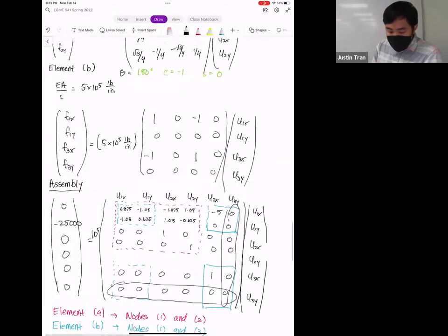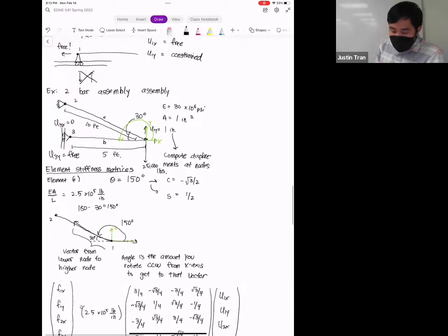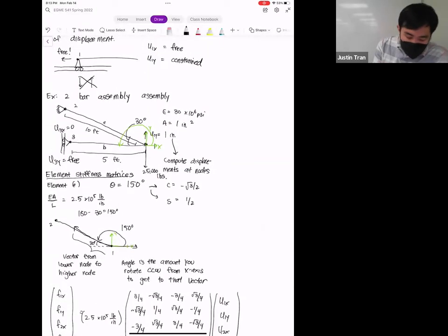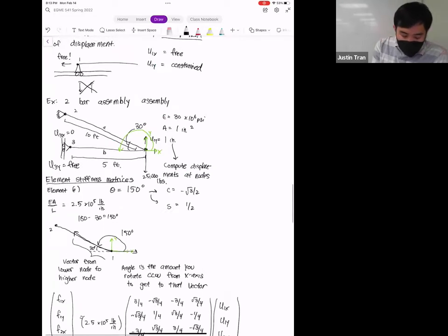So let's go back to node 3. What that tells us is that node 3 here, the y component is under constraint. That makes sense, because if we look back at node 3 in our system, you can see that we're letting it roam free. When we start pulling down on this node with the force of 25,000, this node is not going to be constrained, and it's just going to start moving freely. There's nothing there that's going to really constrict its motion.